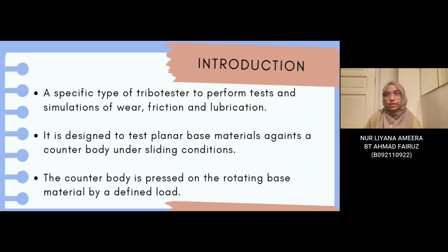So pin on disk is a test that we have to perform to test the simulation of wear, friction, and also lubrication using a tribology tester. The tribology tester is designed to test planar base materials against a counterbody under sliding conditions. The counterbody is pressed on the rotating base material by a defined load.